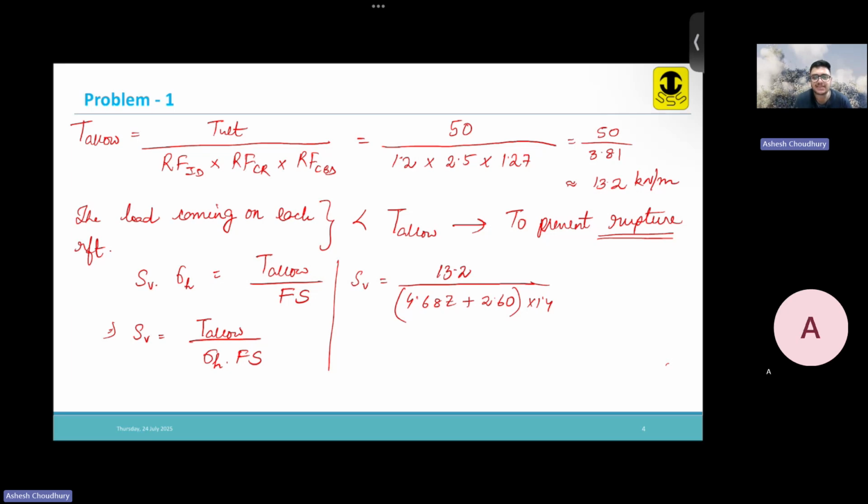You will see that as the depth is higher, the spacing will be lower. It is a denser configuration, so you have to place the geotextile densely. But as the depth reduces, the spacing increases, meaning a scarcer placement of the geotextiles. So you got S_V as a function of depth z. Selecting the appropriate spacing satisfies one of our internal stability criteria, the rupture prevention criteria.